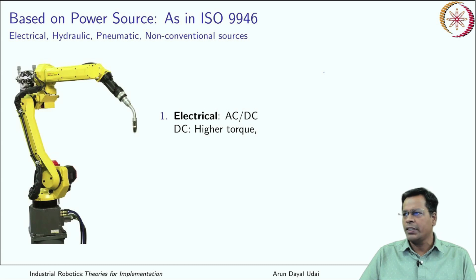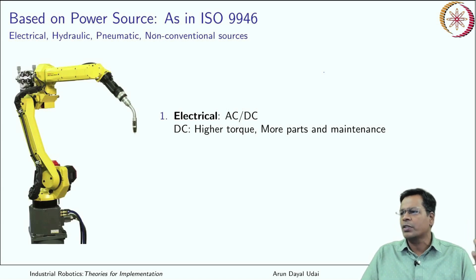A DC motor can normally provide higher torque, mostly higher starting torque, which is very helpful to make compact robots. Because a DC motor normally has carbon brushes within, we'll see the construction of DC motors, AC motors, steppers and various other motors in detail in our next module.